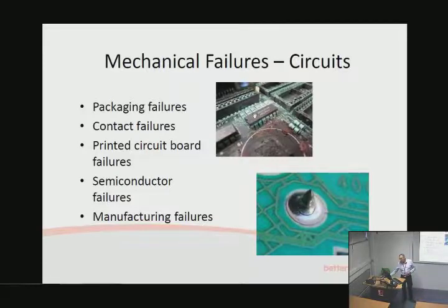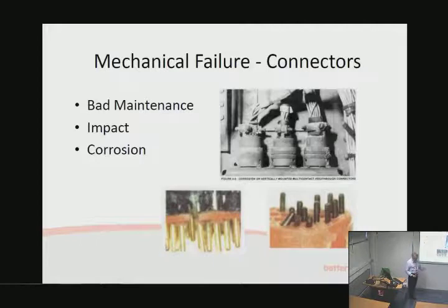This one rather amuses me, in that that's a special kind of mold that lives on PCBs. How about that? This is a microscopic crack in the via, in a pin poking through a PCB, which can cause some extremely unexpected failures. And they can happen for all sorts of different reasons. And then it gets worse when you start trying to plug circuits together, because maybe you've discovered this already in your year's study so far, but connectors are often the electrical engineer's enemy, and they are particularly prone to causing disaster.